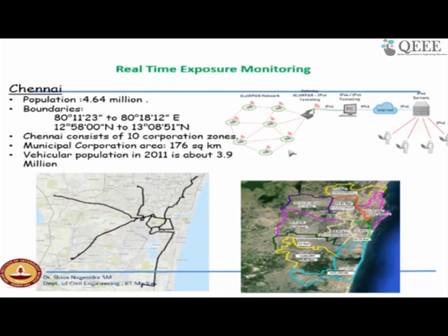So we have two types of standards: emission standards for the source and also ambient standards for ambient air quality management. Now if you want to set up more stations, for example, in a city of population about 50 lakhs, you need to have about 10 monitoring stations. Then one of the questions is where to locate these monitoring stations. The standards are specified for two areas. One standard is meant for residential, industrial and traffic sites. The other one is for ecologically sensitive areas.